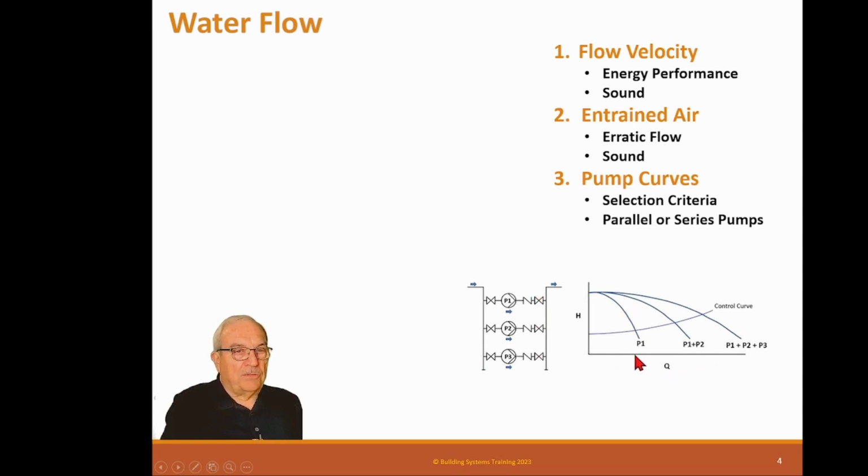So each of these pump curves are like this. If you have pump 1, its curve comes down to right here, and this is the flow at no head, at free flow, and then this piece right here is exactly equal. P1 is equal to P2 if it's got no head. But the minute you put head in it, you notice these are curves. So if you're up here, you'll notice this one right here is the flow, and this one right here is the flow. Well, the deal is this second pump only provides about 80% of the flow of the first pump. As you get 3 together, this one's probably 35% less than the first pump.